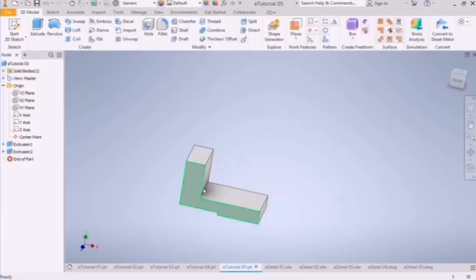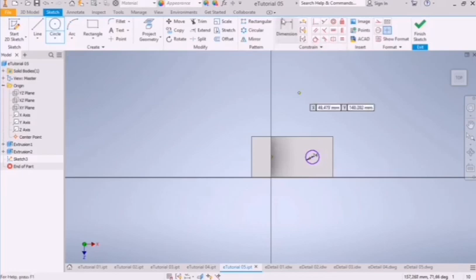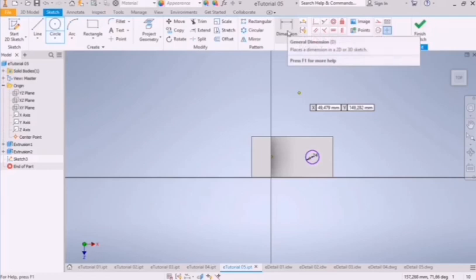And then now again, let's start here and sketch. We still have our center point there. From our center point we'll project 12 times 2, which is 24 diameter, because where they gave us a radius, so the full diameter is this one.